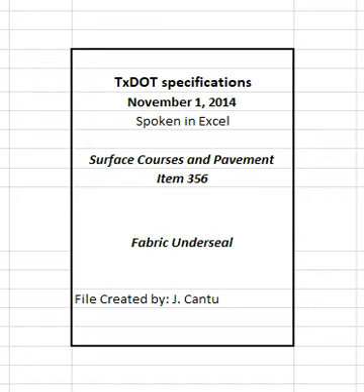4.1.2 Asphalt binder application. Apply asphalt binder with an asphalt distributor unless otherwise approved, at the rate shown on the plans or as directed, within 15 degrees Fahrenheit of the temperature selected by the engineer, approximately 6 inches outside the fabric width, and with paper or other approved material at the beginning and end of each shot to construct a straight transverse joint and to prevent overlapping of the asphalt. Match longitudinal joints with the lane lines unless otherwise approved. The engineer may require a string line if necessary to keep joints straight with no overlapping. Never contaminate asphalt binder.